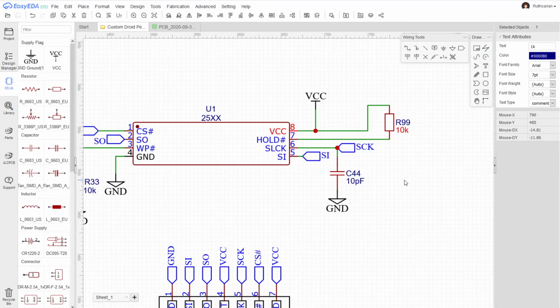And then that power is going to come out of your programmer, and then it's connected directly to pin 7, so then power is going to be coming back in through pin 7 of your programmer.